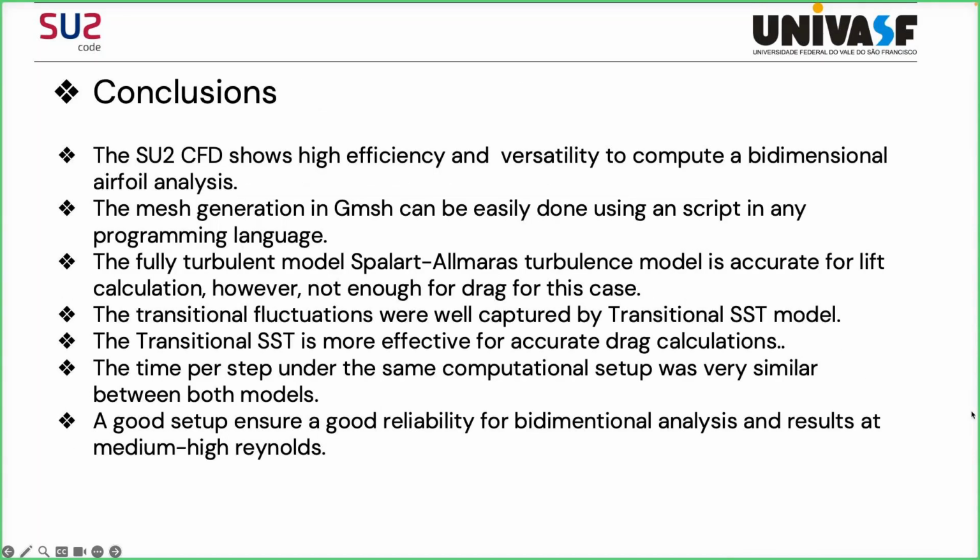In summary, this study demonstrates several key findings regarding aerodynamic simulations of a two-dimensional airfoil using SU2 and Gmsh. First, the SU2 CFD solver proves to be highly efficient and versatile, making it well suited for two-dimensional airfoil analysis across the flow conditions. The mesh generation process using Gmsh also stands out for its simplicity and ease, as it can be automated through scripting in any programming language, streamlining the simulation setup.